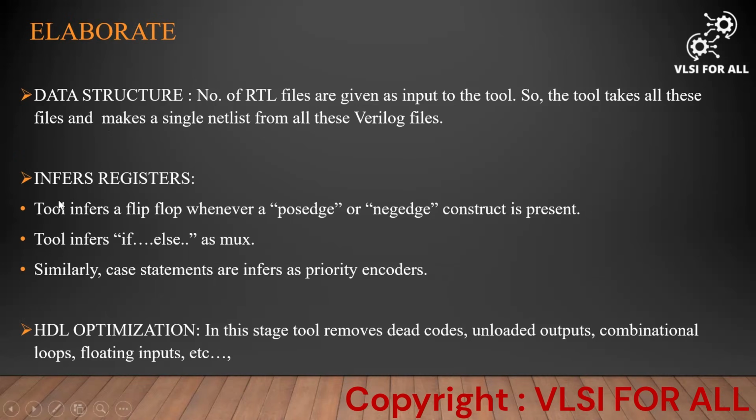And coming to inference registers, in this step, whatever files we provided to the tool, it will read and load those files and that information into the tool. In this step, whenever the tool reads a posedge or negedge in the input file we provided, let's say an RTL file, it will treat it as a flip-flop. Okay, this is the flip-flop, which I'm seeing as posedge or negedge.